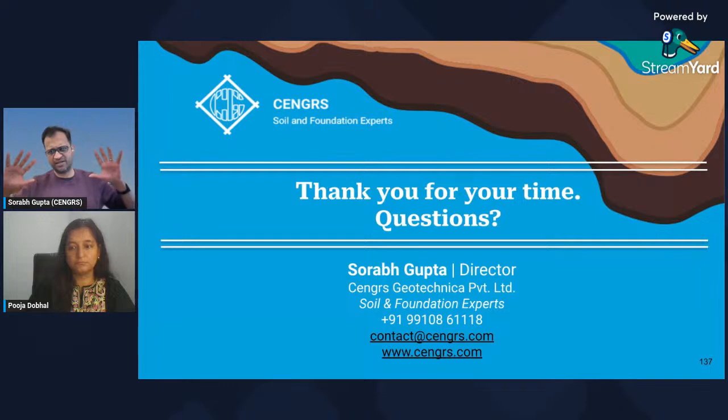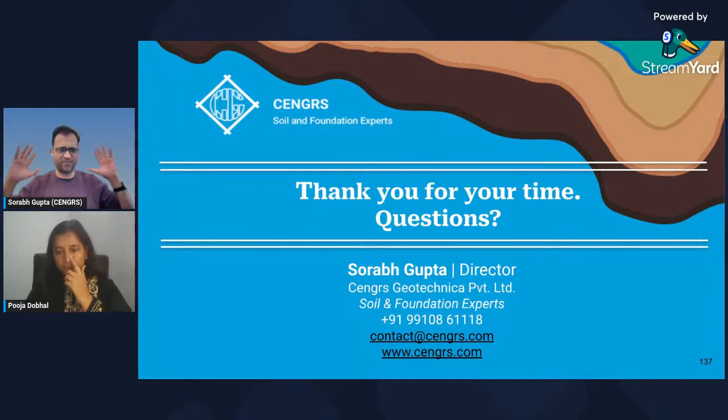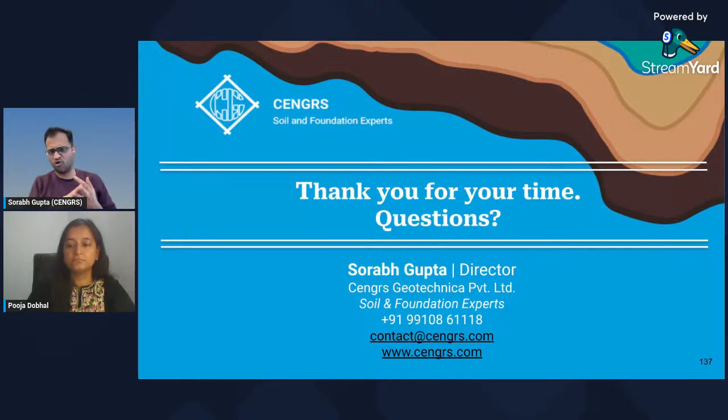Otherwise, especially in the Indian context, most of the PIT we are doing is on bored cast-in-situ and steel piles, because honestly speaking, that is where most of the structural defects actually take place. So yes, it can be applied to auger cast piles, precast piles, bored piles, all kinds of piles, no problem. But the strongest application is mostly for bored cast-in-situ piles.